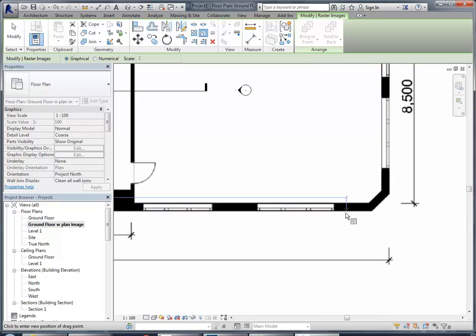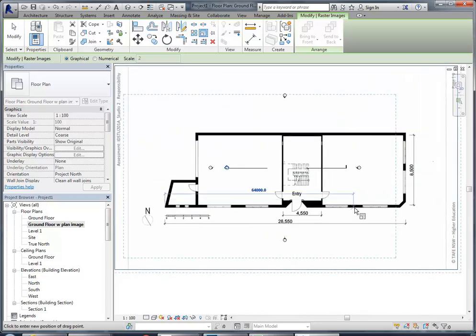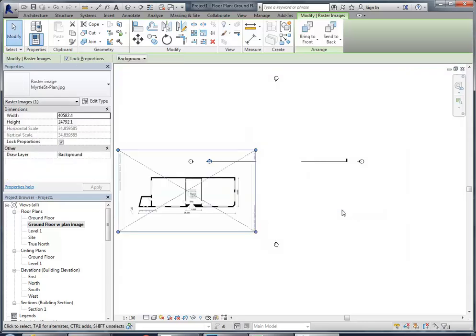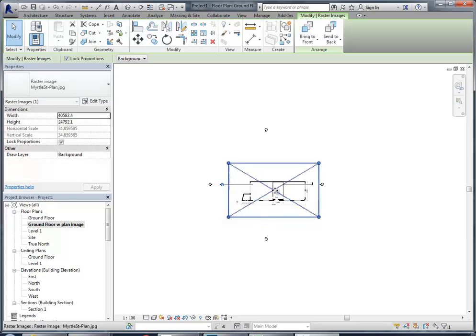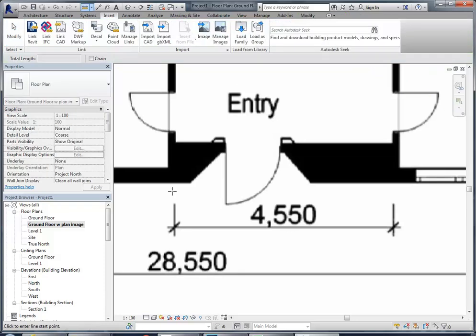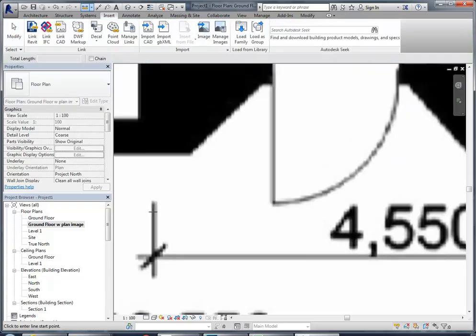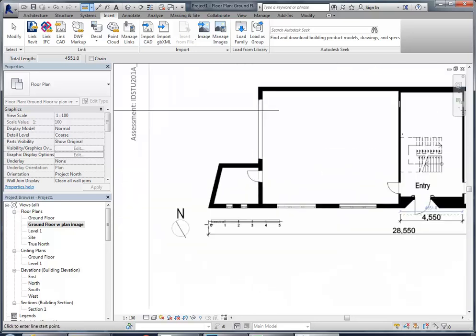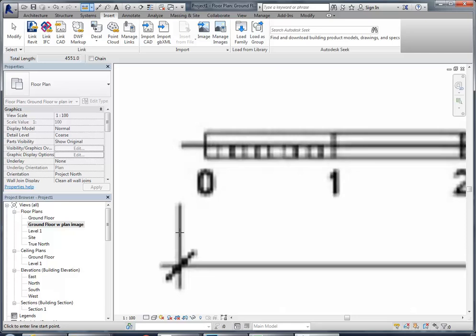And then I'm going to move it back to the left slightly, because I know this has got to scale down, so you can see they're making it smaller. But instead of clicking a point there, I'm going to type in the size I want, which is 28550. Enter. So now that should be the right size, or close enough to it, but I'm going to check with the tape measure this other dimension we've got here. So just measuring across there, 48551, that's close enough. A mil out, I mean most builders don't build that accurately anyway, so that's fine.